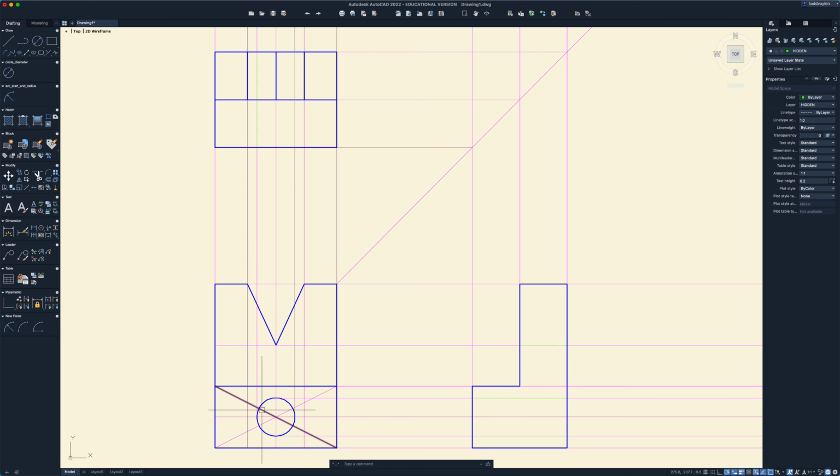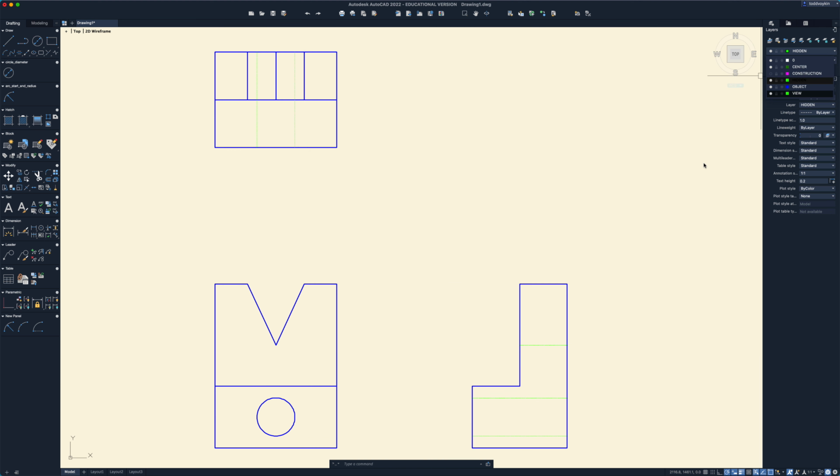Especially on a circle, like this circle happens to have a radius that is a whole number, 70, but if it happened to be like 63.691, a bunch of infinite decimals, you couldn't really create these edges of the circle without using these rays. So it's quite helpful. Now those are the only hidden lines that we have there. So I am going to now go turn off my construction lines. I don't want to delete them. I want to keep them there in case I ever need them again. So I'm just going to temporarily hide them. And there are the